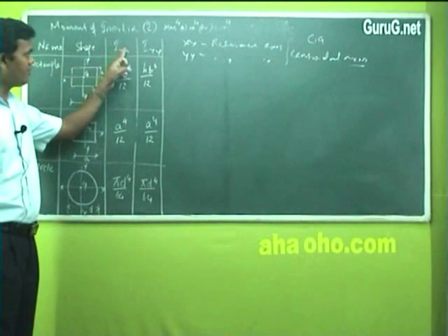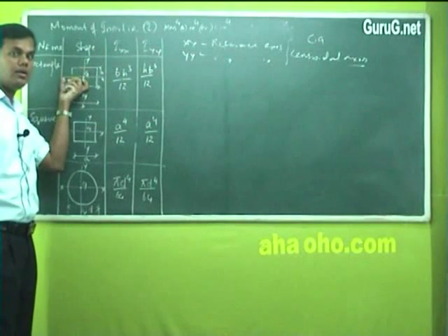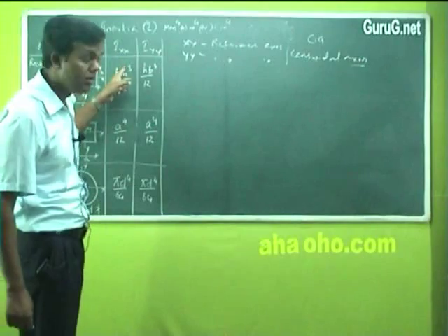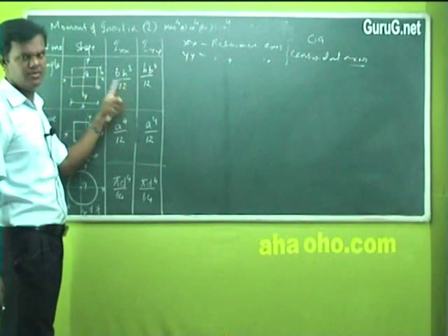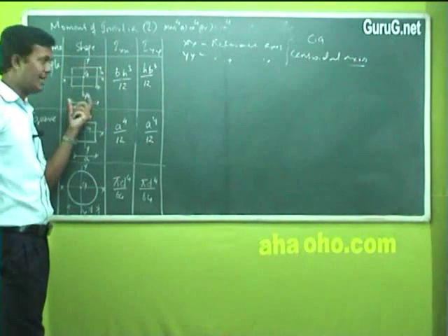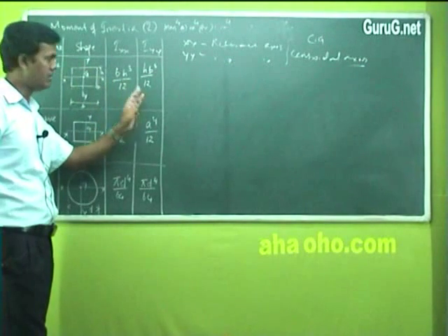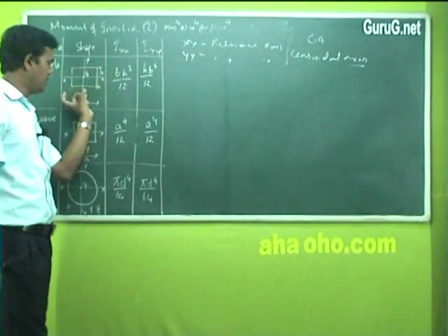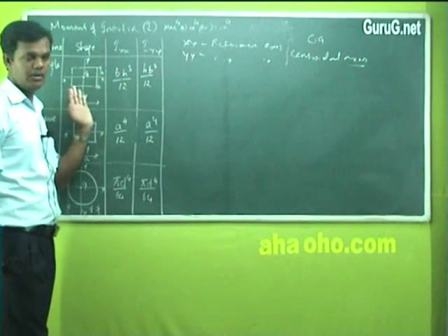And the formula for Ixx, that means for this particular body, if you want to find out the Ixx value, it is the moment of inertia value for this xx alone. The formula is like this. For a rectangle, it is bh cube by 12. What is b here? Breadth. H is height, divided by 12. Formula given. Second formula, Iyy is hb cube by 12. H is first, and the cube is for the breadth, then 12.